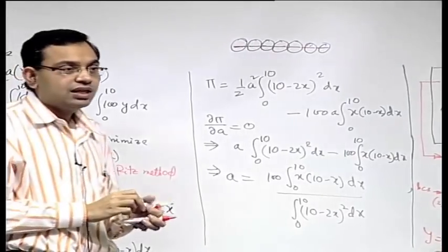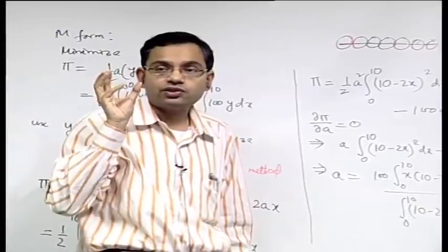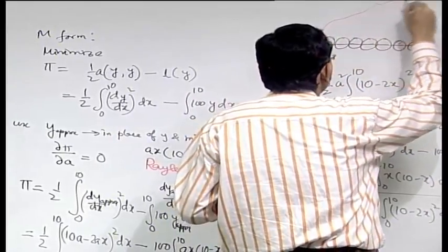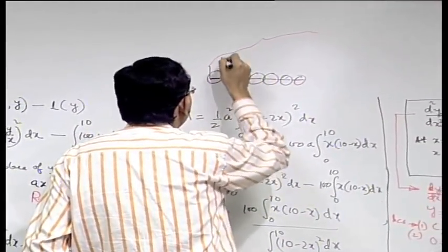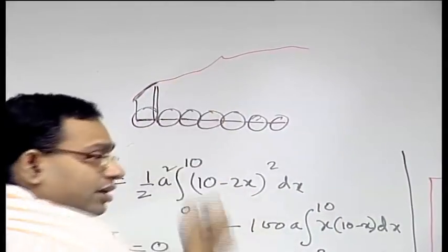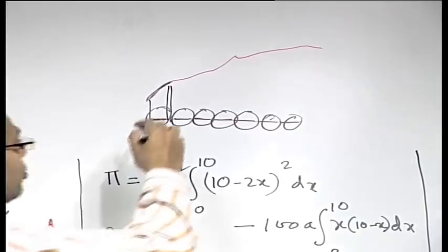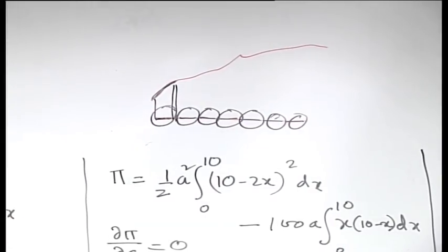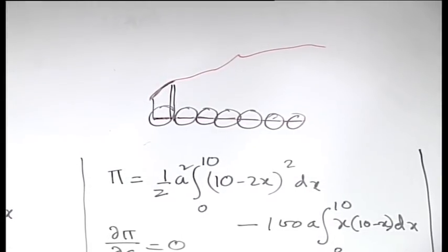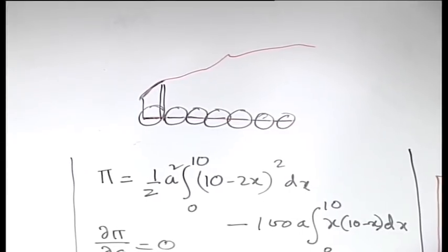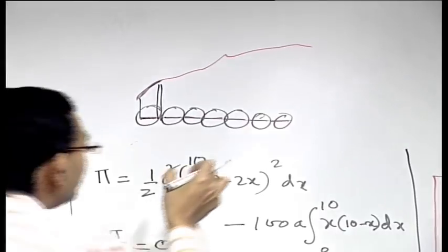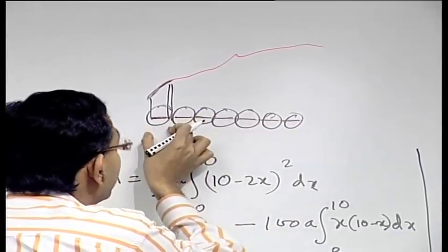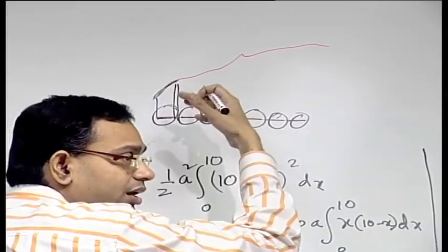So, what you are doing is you are now not considering a global solution, but a local solution. Because you are considering a local solution, your entire global solution may be very complicated, but when you consider a small part of the domain, then this may be fitted by lower order functions. Whereas, if you wanted to do it in one shot over the entire domain, you would have required a much higher order polynomial function. So, you are reducing the requirement of the order of your polynomial function, but the cost that you have to pay now is that you are dividing your domain into a discrete number of subdomains, and for each subdomain you are going for a lower order polynomial to approximate your solution.